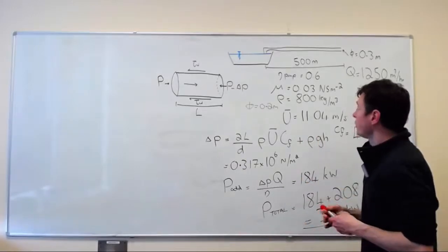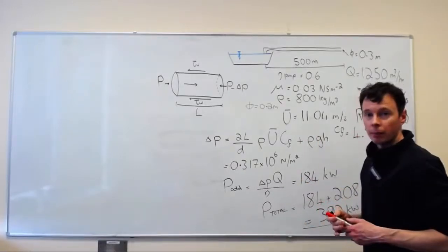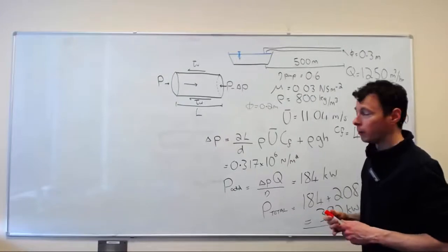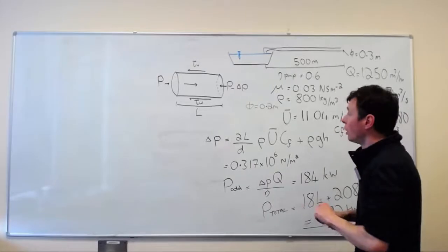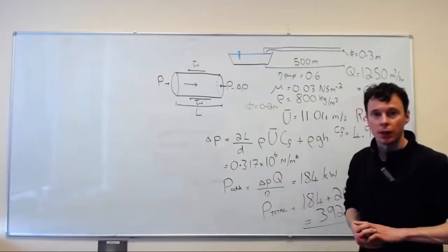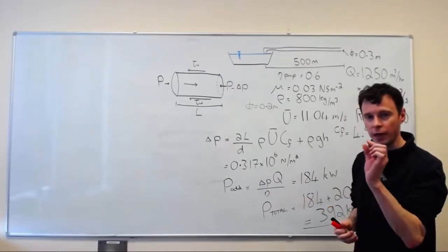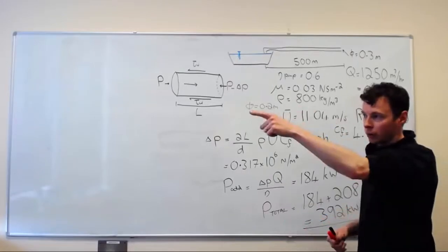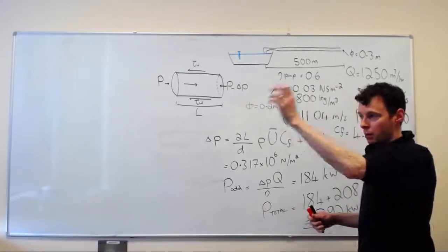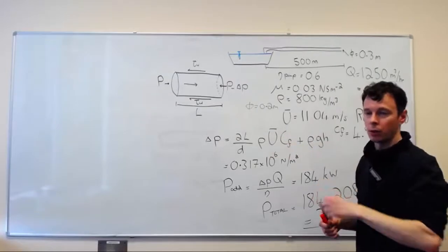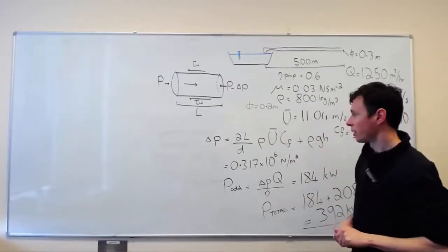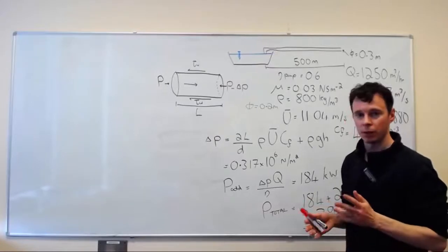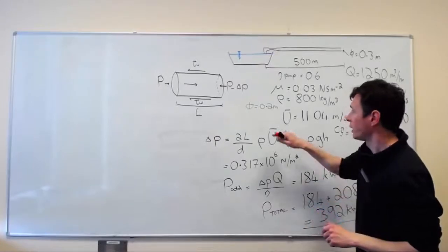So what this means is practically, if you have a certain length of pipe, there will be a limiting flow rate that you can have. And I did some work on this a few years ago, little anecdote now, with some architects in London. They wanted a water feature, very, very narrow jets, firing incredibly far and staying basically as coherent jets of water. So no dispersion or anything like that. So we created a manifold and tested lots of different pipe types and nozzles, and we found exactly that.